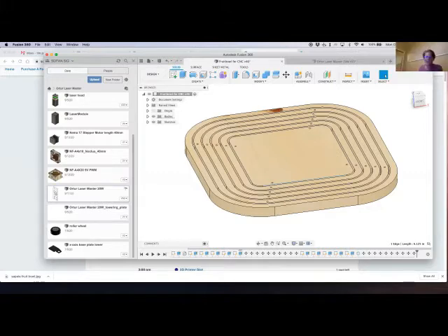For a piece like that, what worried me about the 15-degree is I found that sometimes the act of clamping it together caused warpage, because you actually forced too much material together on one side of the finished board. Well, I look forward to learning more about V-carve, because it's just another tool in the toolbox.